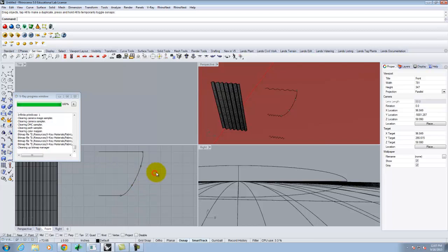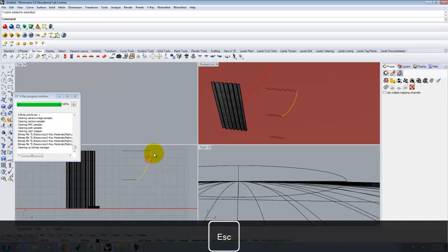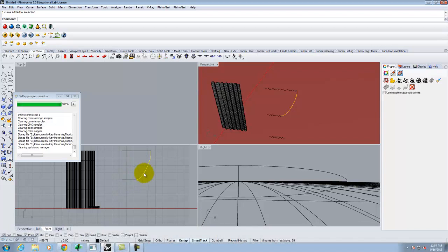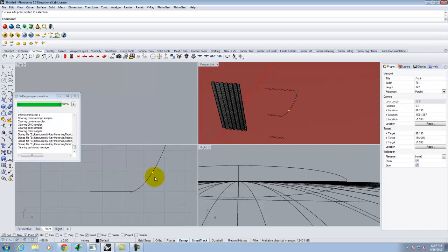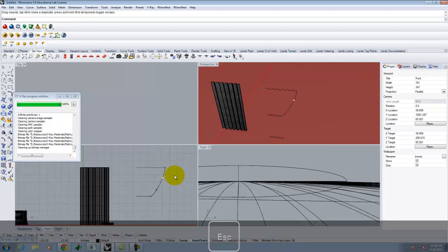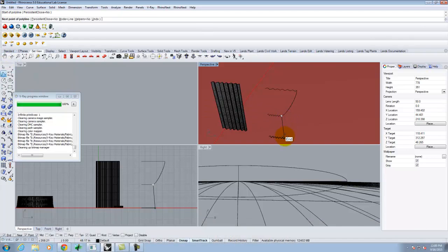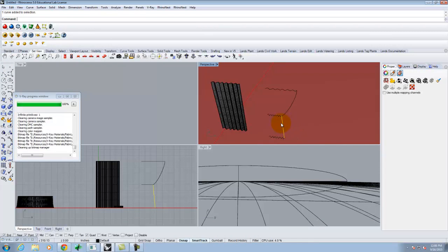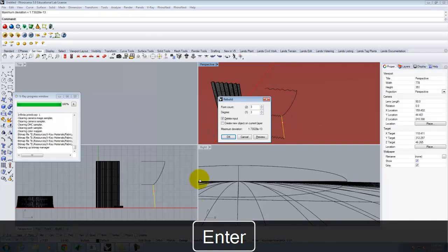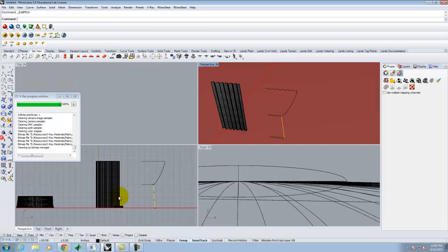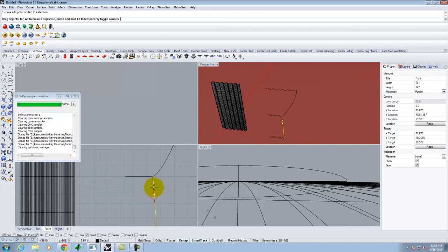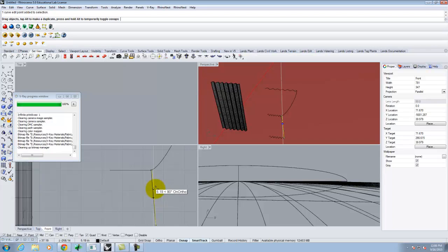I'm going to have it so it comes down. And again, it helps if you actually look at a curtain to see how fast it comes into that point. I might be a little bit too fast. Pull this back a little bit. More like that. All right, it's coming in there. Next one that I'll do is from this point to there. Let me rebuild it with 3. Say OK. Turn my edit points on. And really, there's not too much to this one other than we want to make it pinch in a little bit more to that point.